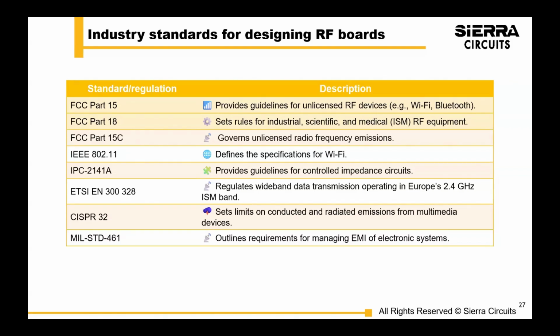So my ask, the learning that I had this week that I want to share, is that the more guidelines you can put on your drawings of what you're expecting, that will set up your fabricator for success from the get-go. So know what's important to you, and then make sure that note is on the drawing and that detail is there, so that you're starting from the beginning of your iterations of prototypes with that expectation.